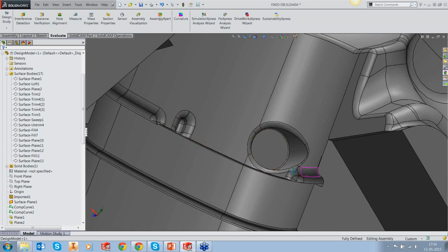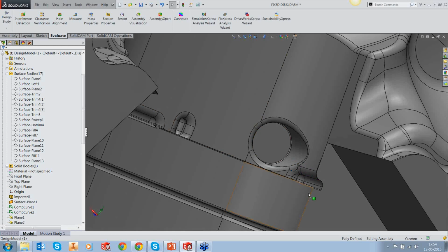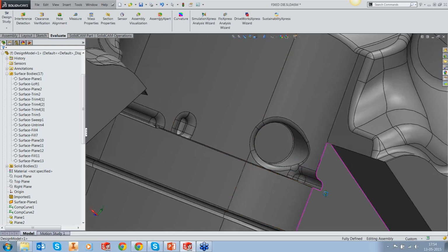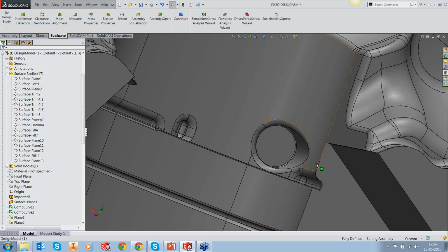There is a small rib out here. Again, if I'm trying to use, let's say, an 8 diameter tool, it'll try to get into this and slow down my machining. Apart from slowing down the machining, these small speed breakers, as I call them, on the tool path will actually cause more harm to my tool. It might chip off when it's trying to get into this area.